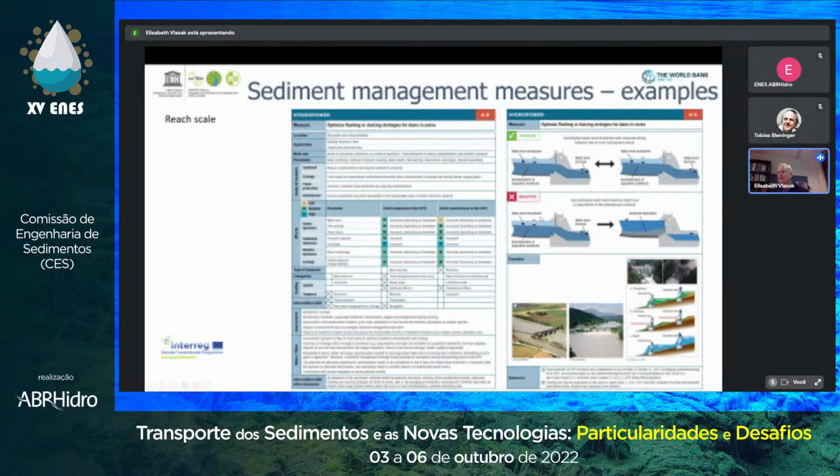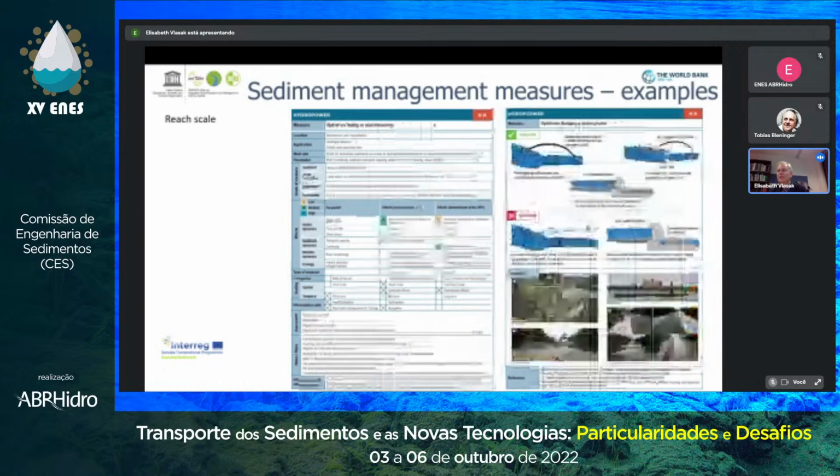If you have runoff schemes in a series, of course, there is then a certain coordination needed for the water level drawdown with an adequate timing between the two hydropower plants. So you need to know the flow time, but also the transport time for the sediments. You wouldn't want to erode some material in one reservoir and then get deposition in the next one. Rather, you want to get the sediments through, which is maybe not possible for very coarse material, but for fine material it should be possible.